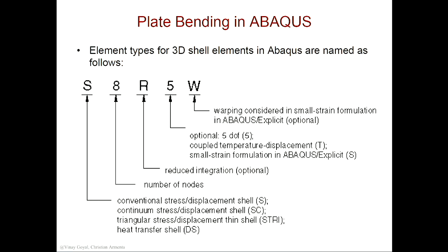K6 rod? The reason is because the formulation there has 5 degrees of freedom, and you have a drilling degree of freedom, so the drilling degree of freedom is the rotation about the z-axis. Remember we didn't have one, right? So what's going to happen when I invert the stiffness matrix? I could have a singularity. So you understand what I'm saying?